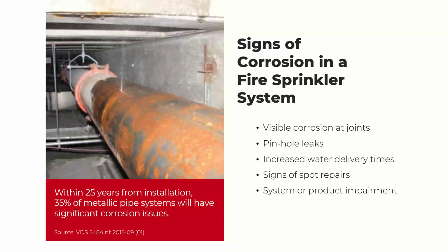But from all the empirical data of installation, what we're seeing is that corrosion is a big issue, and it can be handled in a variety of ways, from good product design to good system layout and design and installation, and in addition to that, an adherence to the standard practices as defined in NFPA 25, the inspection, test, and maintenance of systems. And this is an ever-increasing document that focuses on the proper handling of systems.